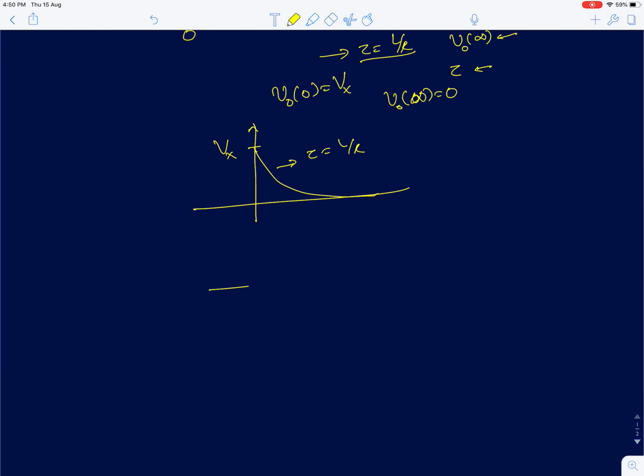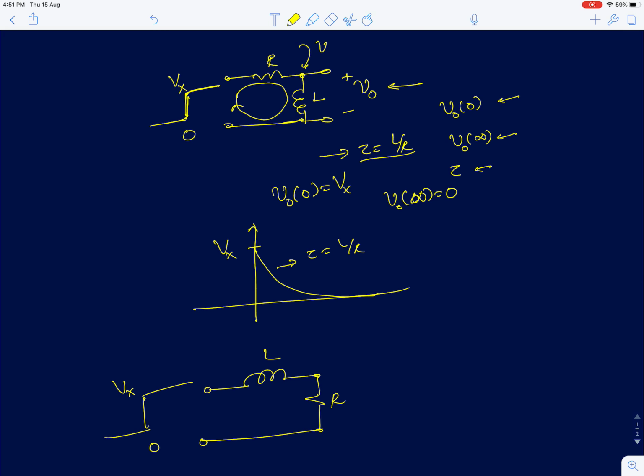Okay. Now when I replace the inductor with a resistor, I just interchange the resistor and inductor positions. Now in fact, in the same circuit, I'll just go back to the first circuit. In the same circuit, if I ask you to draw the waveform of the current, now that you know the voltage across the inductor, you simply integrate the voltage: use the equation 1 by L integral V0 of t dt, which will be nothing but the current through the inductor. So I can use that and compute it, or we can just use a simple first order analysis.